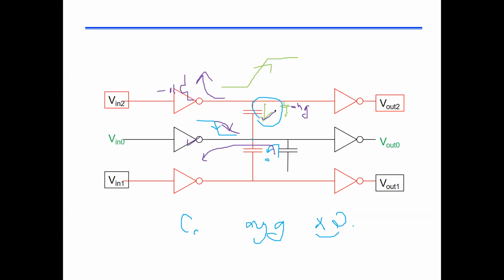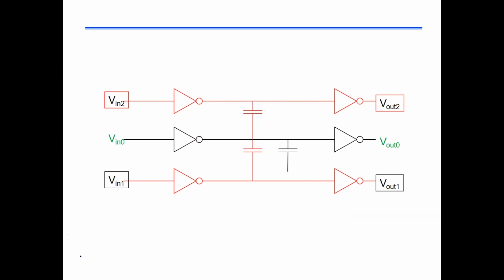It will charge this node and the coupling capacitor. So this will send me some current that is coming from VDD. Meaning the current from VDD through this PMOS is going through this and then coming back to my own capacitive node, right? Whereas I am trying to discharge, it's as if somebody is throwing water at me. It is as if this guy is throwing a charge and I'm trying to discharge.